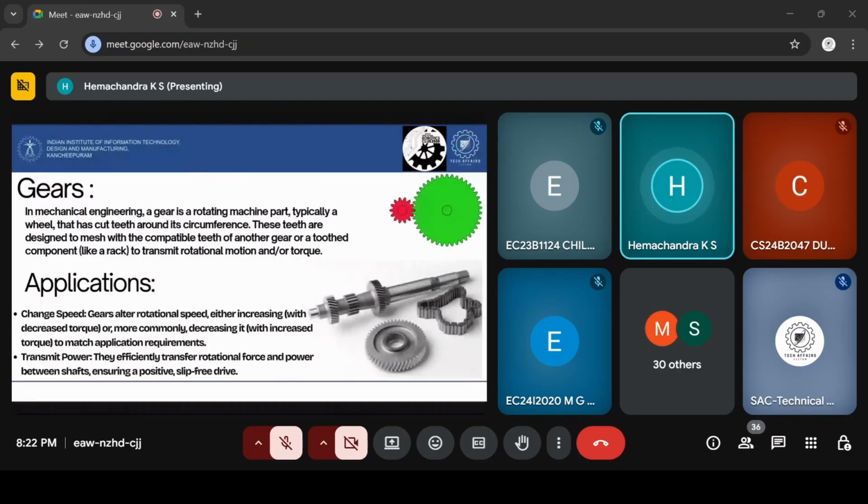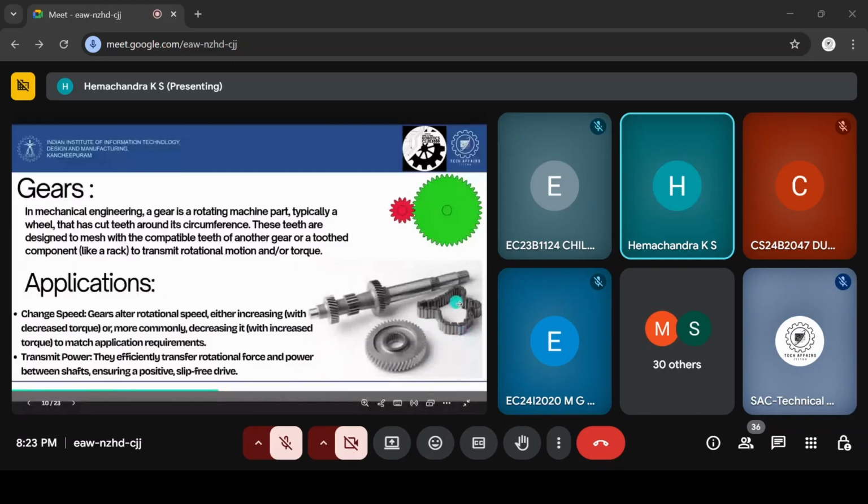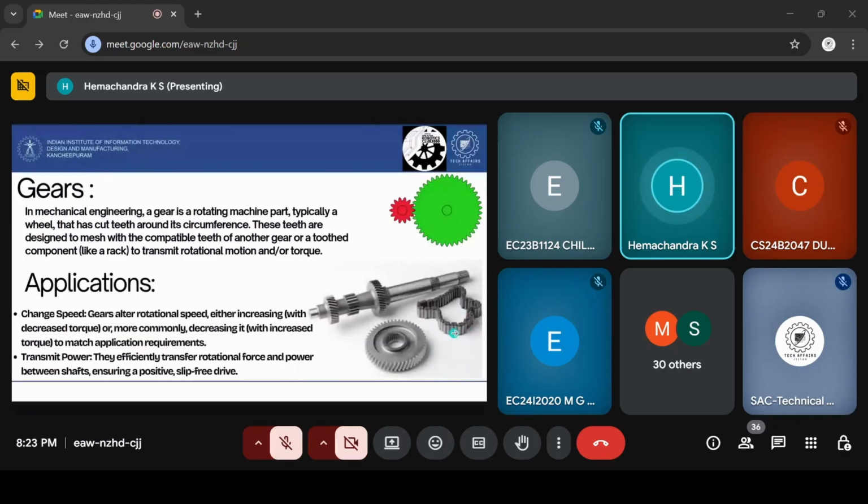In the same cycle, between the pedal and the back wheel, there will be a chain system, as shown here. You can ask, the chain also will change the rotational motion. But the thing is, there are inefficiencies when we use a chain. A gear is very, very efficient. It's 99% efficient, whereas a chain is only 95% efficient. And there will also be some slippage in a chain.